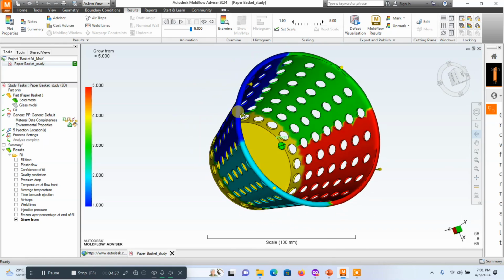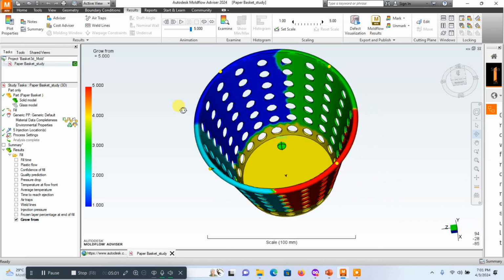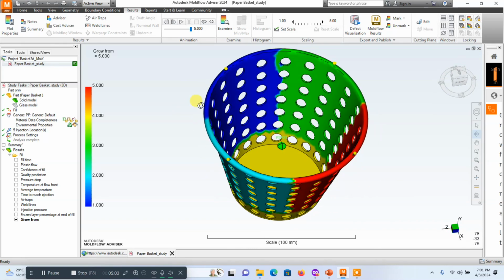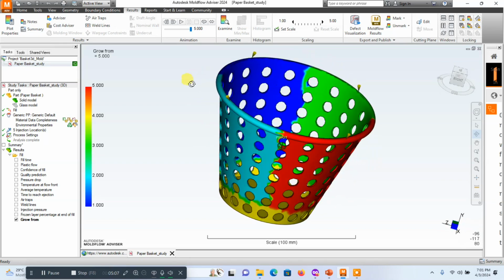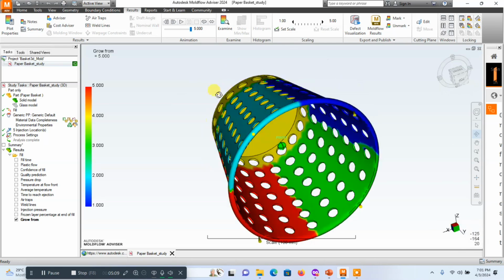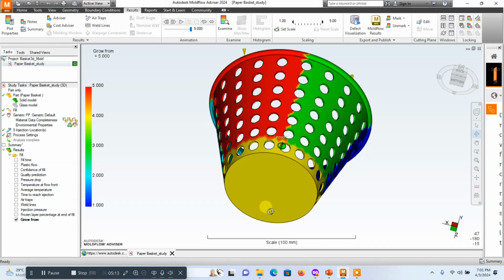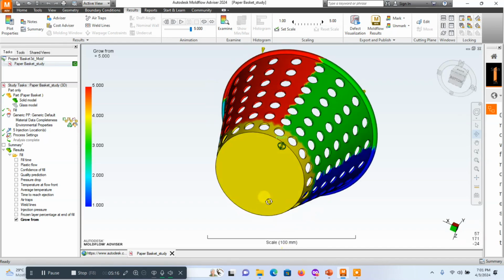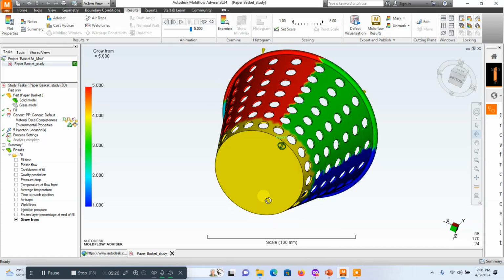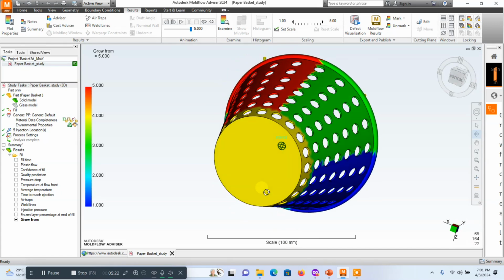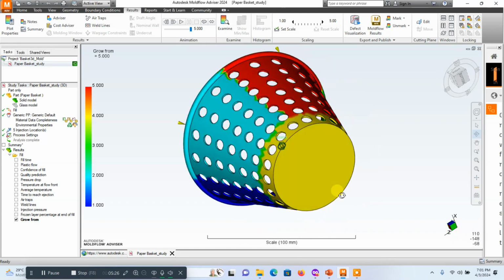Now, let's look at quick things you can look out for. One, you can see that the result indicates an equal distribution of colors, which will have a uniform filling pattern and be balanced. If the distribution of colors is not equal, then the flow is unbalanced. In this case, the distribution of colors that we're seeing in this basket is balanced, and it is in complete, successive sequence. One finishes before the other picks up. So these are very basic things that you should look out for.